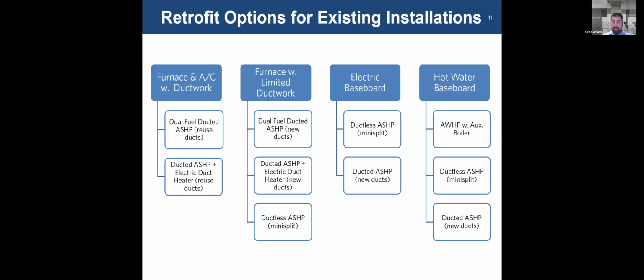You can put a heat pump system in for a minimal amount more than you would just a plain old air conditioning system. You can get some of the added benefits of that heat pump heating in milder climate. And once the heat load of the house exceeds the capacity of the heat pump, you could still use your hot water baseboard system, provided that it's still in good working order.